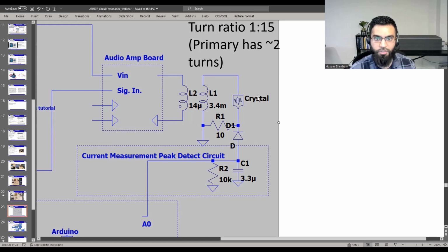So we have this crystal. All right, the transformer is used for impedance matching, which basically means you have to increase the voltage to drive a higher impedance load. There's a question in the chat about why we're using the transformer. Well, because the voltage is not sufficient, but that also means the optimal impedance load of the amplifier is not sufficient. So impedance matching is almost a synonym of voltage, as long as you have enough current to drive the whole thing.